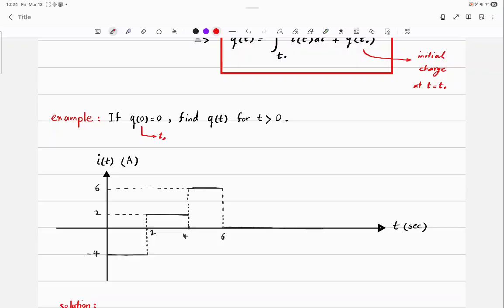So when you see a negative in the expression or in the number associated with the power, it doesn't mean that it's bad or good. Okay? It only means that whatever you had initially in mind, it's not doing that. For example, if you're talking about absorbed power and get a negative number, it means that that element is not absorbing power. It's actually delivering, supplying power.